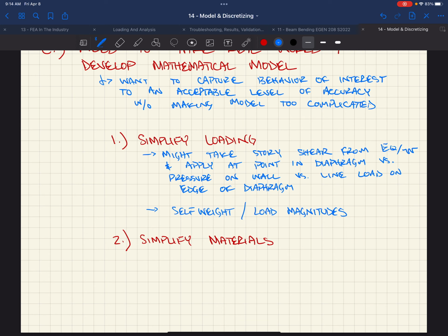Is that typical, or do you have a typical seismic anchorage for a lot of different veneers? I mean, in their case, it's probably a very proprietary system, right? Like a solar wall that you see on the side of a business building, it's basically just big black perforated wall panels. The air travels through and the sun preheats it. It's an energy efficiency thing, right? So that's made by a specific manufacturer. They plug that as, use our product. And as part of that, they do a bunch of testing to make sure that all of the system, from the actual panel down to the connection to the structure, is adequate for all of the required loadings.